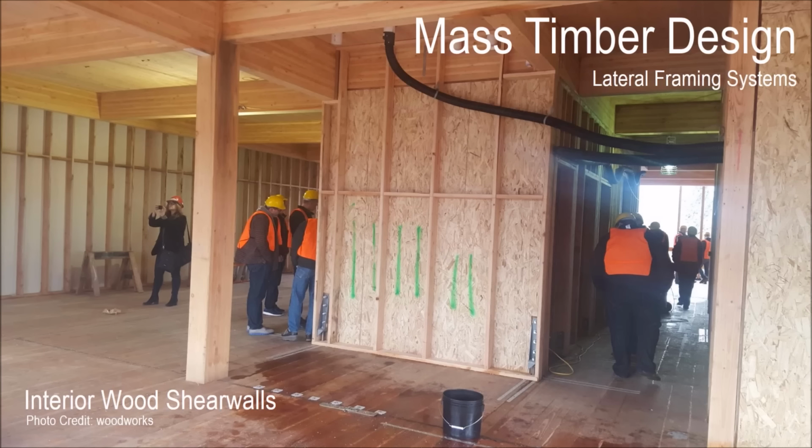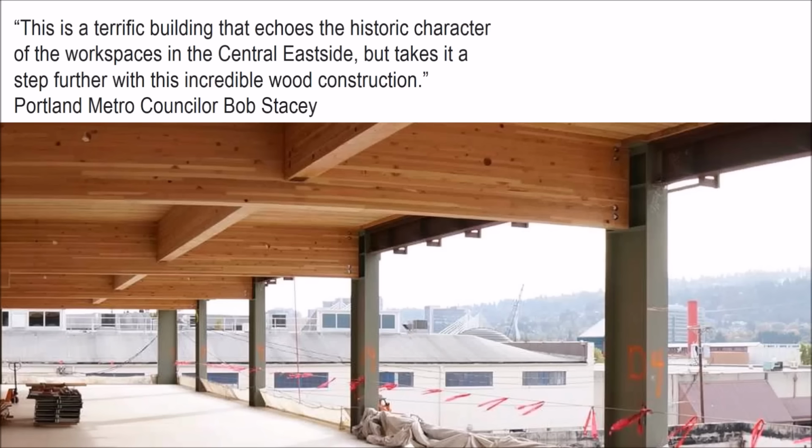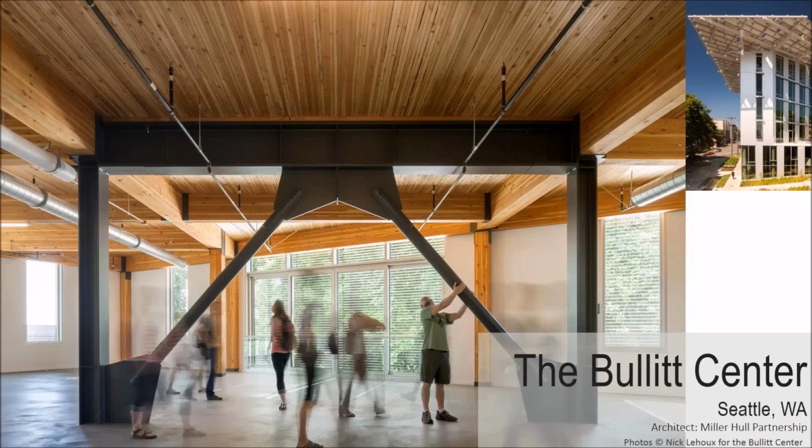Although, if you're doing a CLT floor system and you don't have places in your floor plan for shear walls, you can combine a CLT floor and a glulam frame system with a steel moment frame, as in this project example. The Bullitt Center project in Seattle used this all-wood framework for gravity loads on the upper four stories, and could use that with a steel brace frame system.